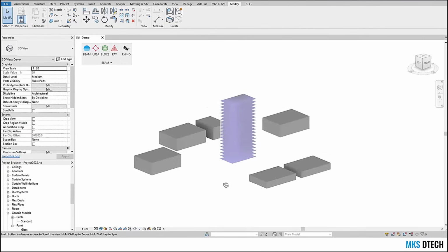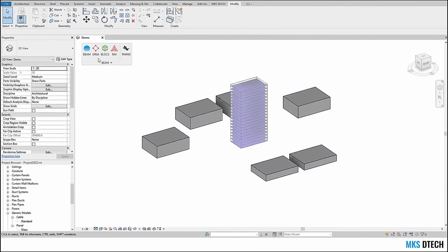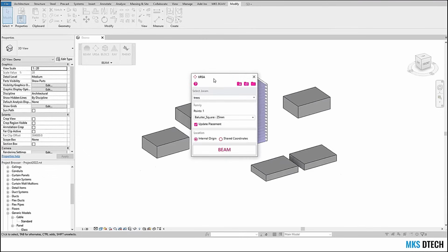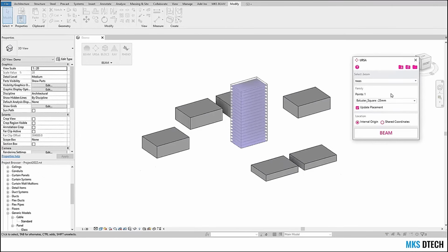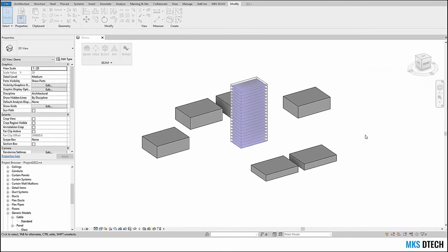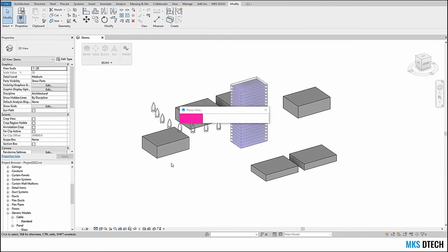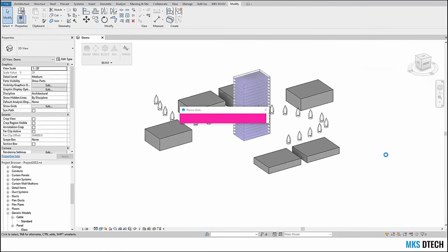Go into our Revit file, and at this point, we are going to use a specific type of family that we haven't used so far, which is 1 point. So normal Revit families, not adaptive components, usual Revit families, nothing more than that. We can see in our Revit file, in our dropdown, we have this planting RPC tree. So we're going to use this family and place our trees on those points.